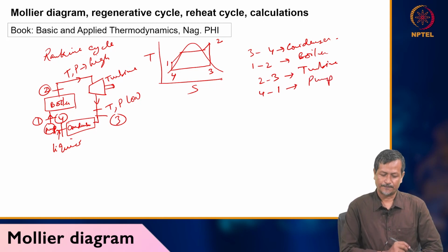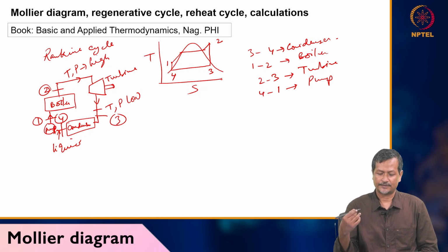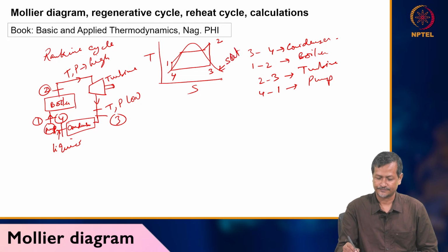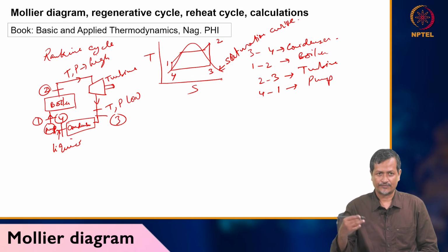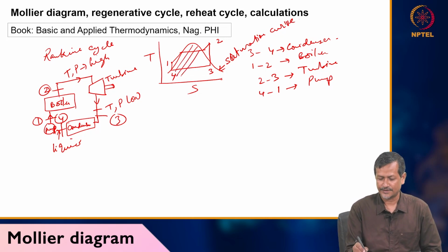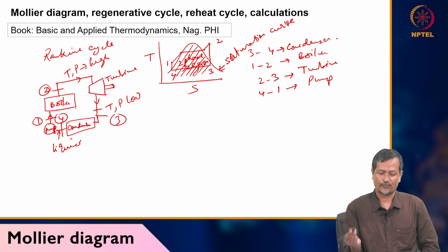Okay, so turbine will be working using steam only. So normally the point 3 will be on the saturation curve, this is called saturation curve, or it should be outside of the saturation curve. Inside this zone is called two-phase region. So point 3 should be outside this two-phase region, and 4 will be on the saturation line or outside of this two-phase region.